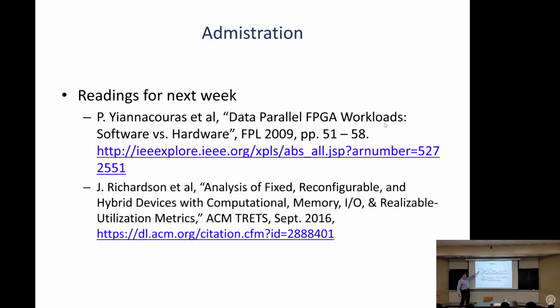And they actually implement both systems on an FPGA. So it's not trying to say how efficient a hard processor is. It's basically trying to say, for the compute model of a processor where you have instructions that tell you what to do, how efficient is that versus building hardware that just does what you want. They're both built in an FPGA, so all the programmability overhead of an FPGA is common to both. I like this paper because it's one of the few, or maybe the only paper I know, that tries to rigorously separate that out. What does it cost for us to be programmable in a processor-style way?